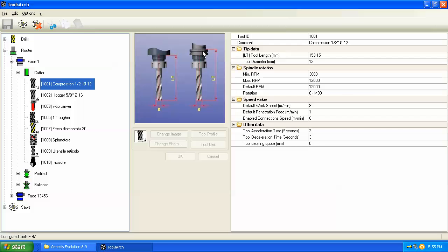So remember, you have to factor in from the shoulder of the holder all the way down to the tip of the tool. Sometimes you may have to make 2 measurements with your calipers. If you have calipers that are long enough, you can measure from the tip of the tool all the way to the very top of the tool holder, which isn't shown here. On an HSK holder, it's always 25 millimeters from this shoulder to the very top. So you can measure the entire tool length, holder and all, and subtract 25, or if your calipers aren't long enough, you can make 2 measurements.